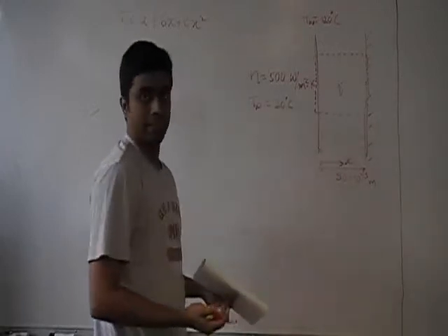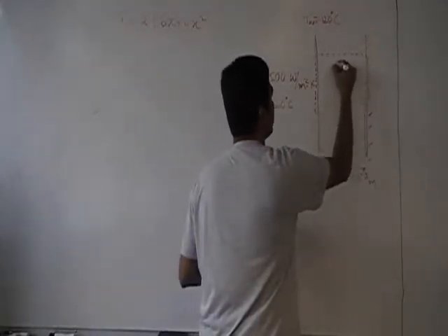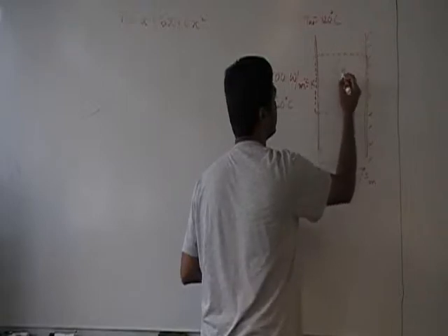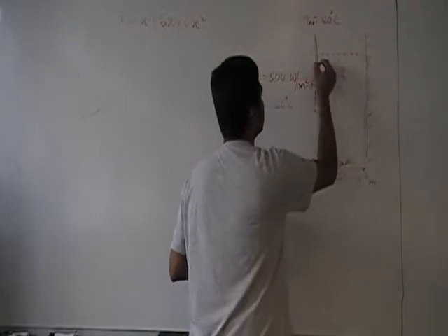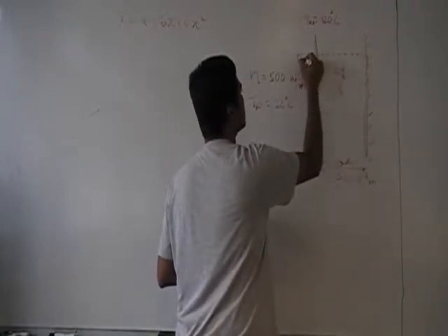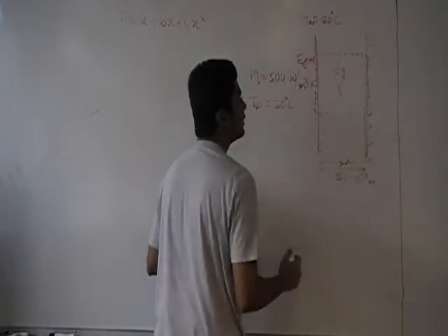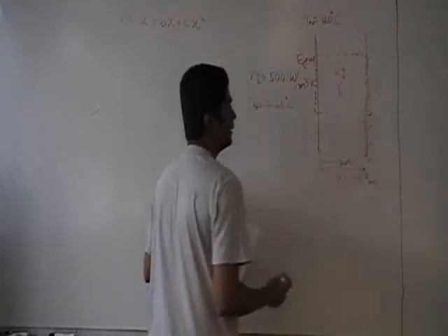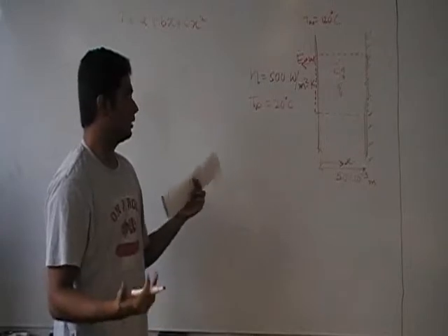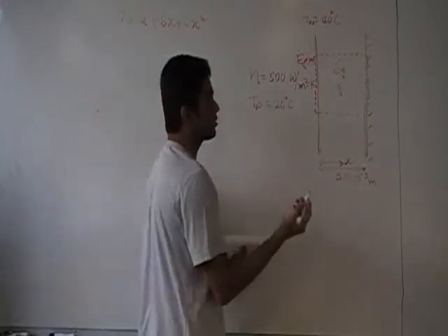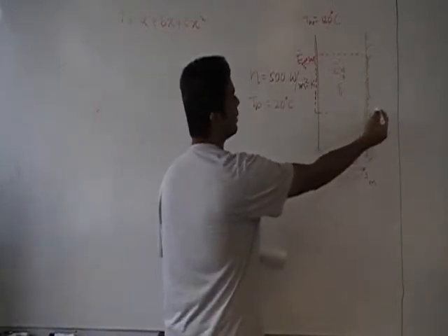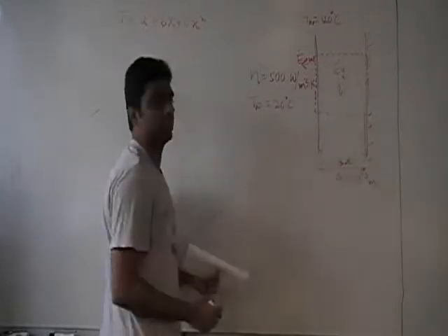So if you try to set up an energy balance here, you have an energy generated term here, E g. There's an E out that goes here. It is given that it's a steady state problem, so there is no E stored and there's no heat coming into the control volume here, so E in is 0.